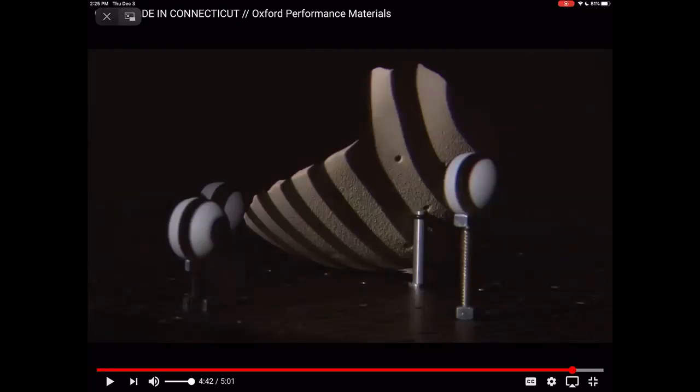Because remember, we talked about you design it in the CAD, right? You print it, but then you need to measure exactly what you made. And so other than printing something and putting it in the CT scanner, using structured light is another way to get dimensions of the object. Or if you've ever heard of something called a FARO arm, which is a mechanical way to measure the dimensions of an object. Basically, it traces out critical points and then reconstructs a 3D model of a real object. And so they've just used structured light in this case.